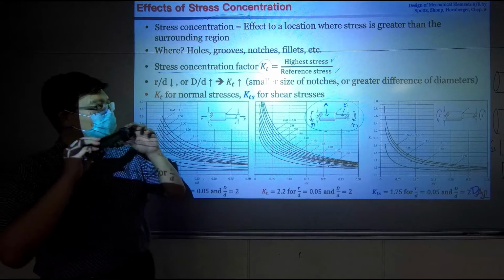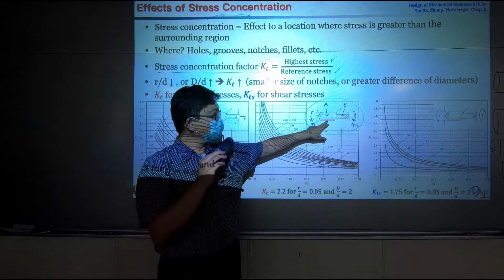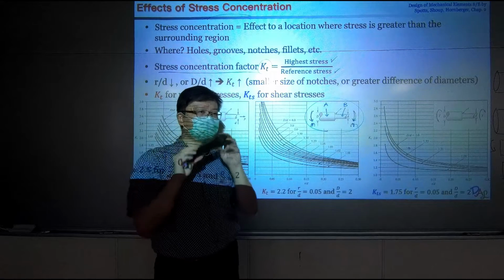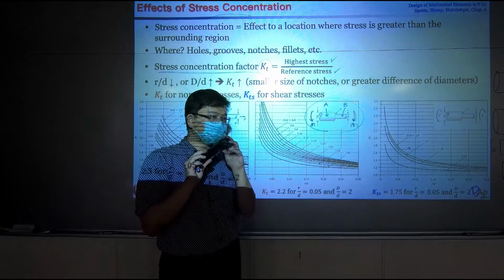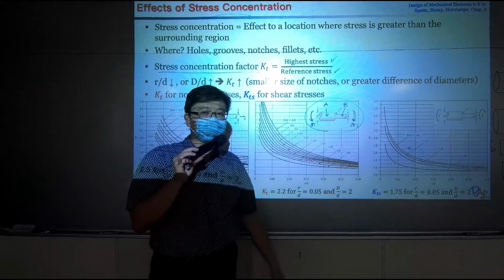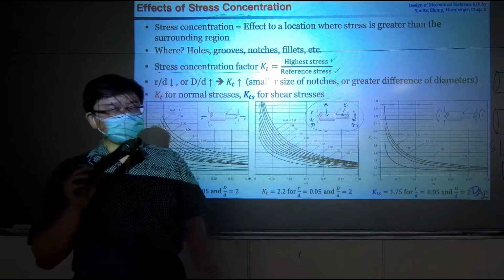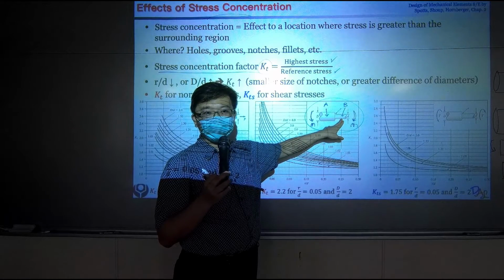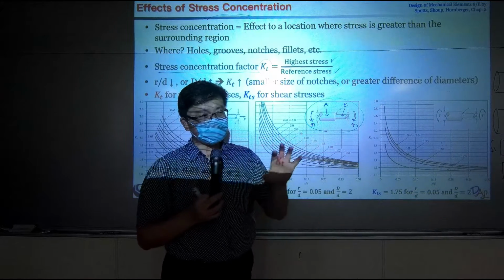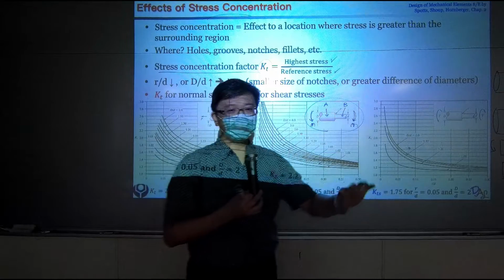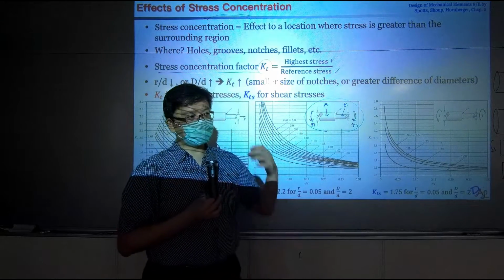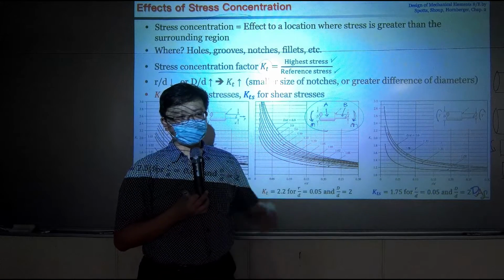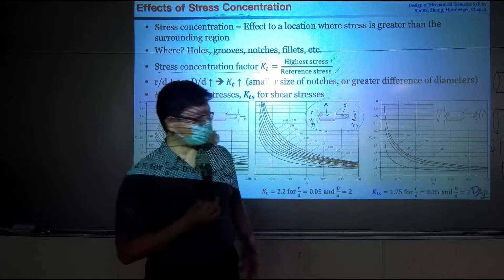I have a cylinder like this, two different parts, different diameter, same bending moment, but which one carries greater stress? B, yes. Then can someone tell me why? Smaller area. Yes. Basically, a smaller area to carry stress. When you have a smaller area to carry stress, the area tends to have greater stress, greater pressure.